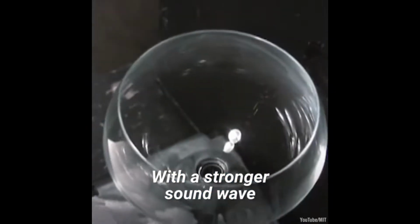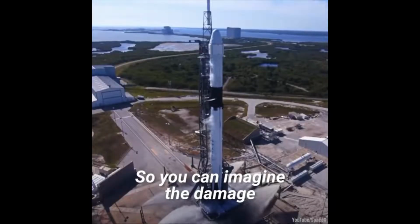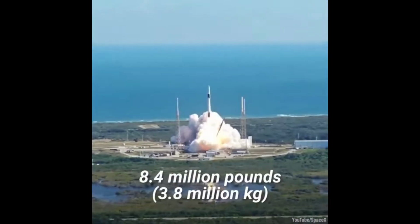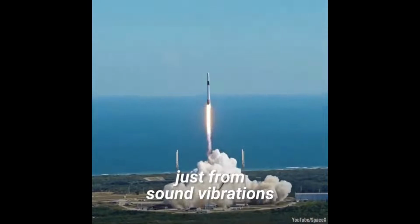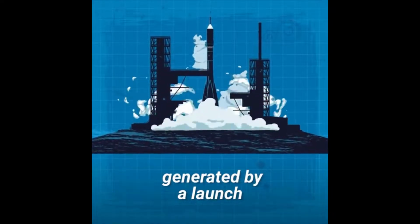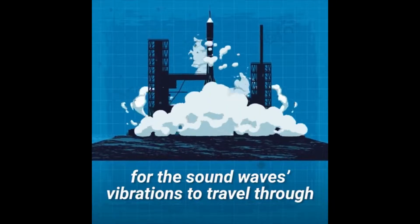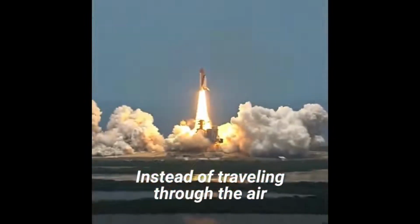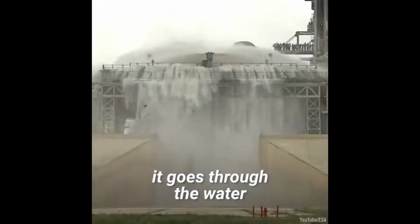With a stronger sound wave, a stronger vibration is produced, so you can imagine the damage that a rocket producing 8.4 million pounds of thrust could cause just from sound vibrations. Water mitigates a good deal of the acoustic force generated by a launch by acting as a medium for the sound wave's vibrations to travel through. Instead of traveling through the air and hitting critical equipment, it goes through the water.